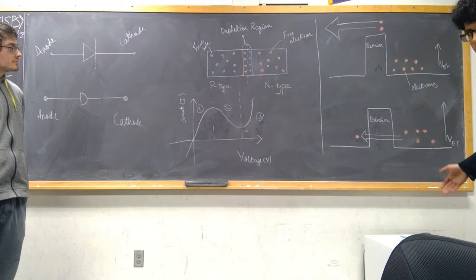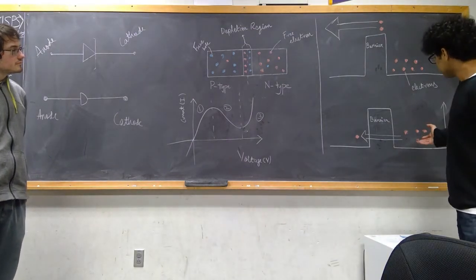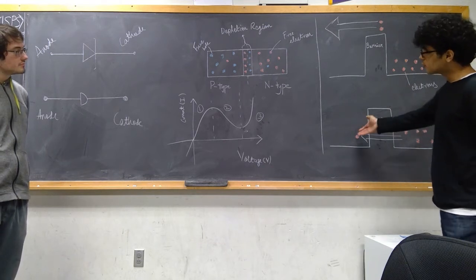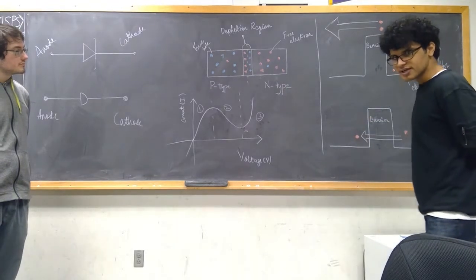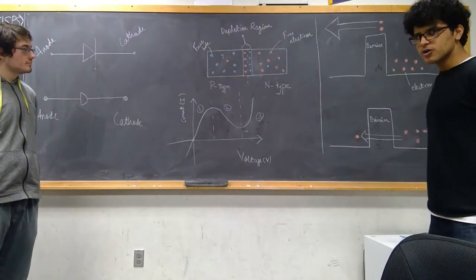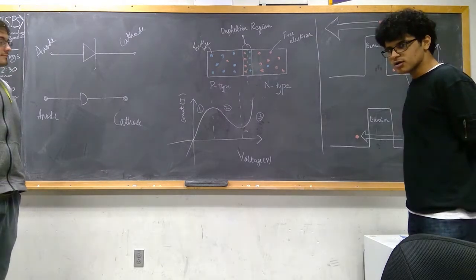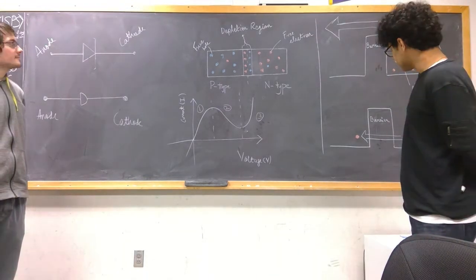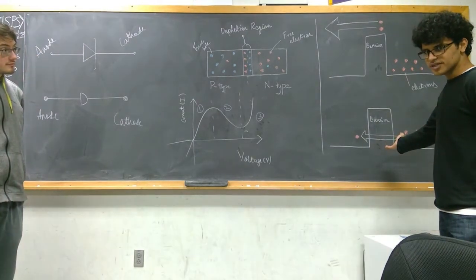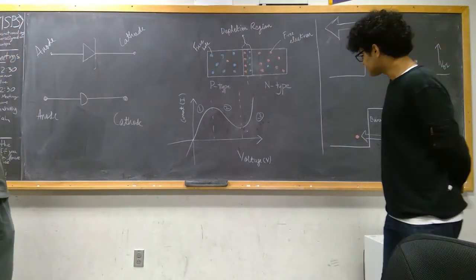In a tunneling diode, this does not happen. When a small voltage is applied, electrons on the n side of the semiconductor can tunnel through to the valence spaces in the p side of the semiconductor. This tunneling of electrons is possible due to the dual nature of matter electrons possess. As we both know, electrons can behave as a particle and a wave at the same time. Thus, when barrier widths are of the order of 1 nanometer or less, electrons are able to tunnel through them very easily.